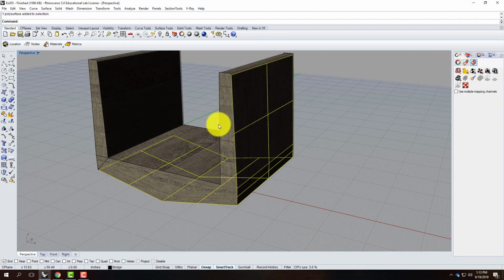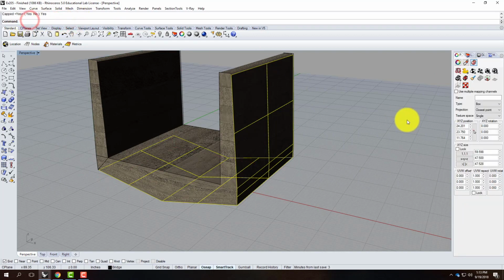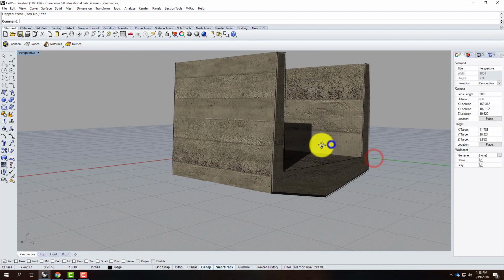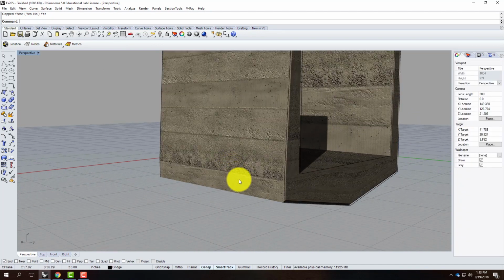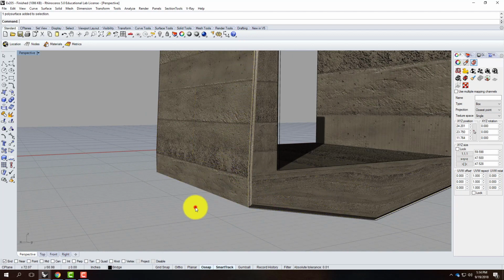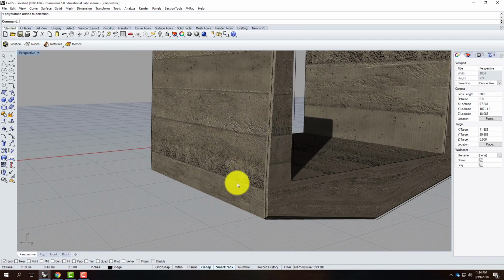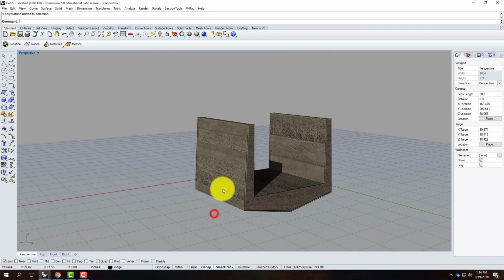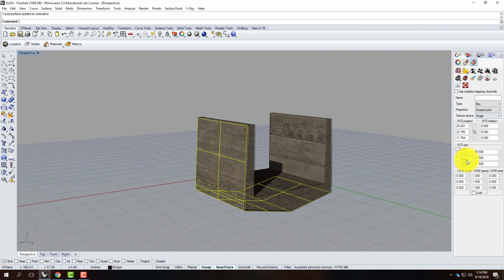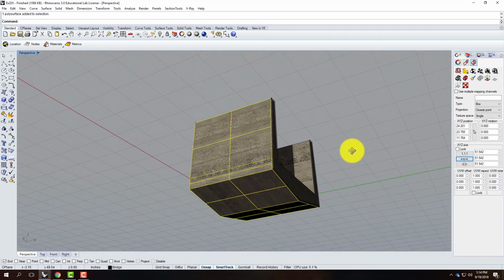And this is roughly box-like, so I'll use a box. And we'll say, yes, we want it to be bounding box, world, and cap it. So now you can't even tell the seam where this transitions into that, because it flows seamlessly through. That's the idea. So it doesn't matter that there's a change in your plane right there. So with that selected, let me also do x equals y equals z to make sure it's even on all parts. There we go.